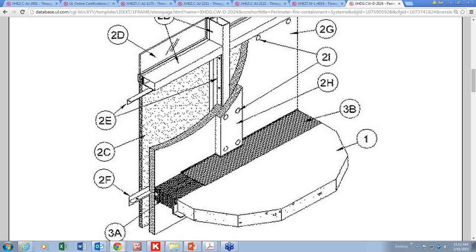So how can concrete block work with granite or some other fire-rated assembly? This fire resistance rated assembly could come all the way out to that area and not have a gap or a chimney. The next question is, what happens with foam insulation at the exterior skin of the building in the NFPA 285?